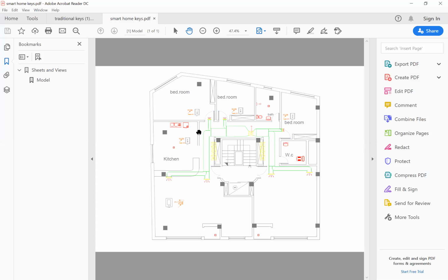On mode number 2, for example, during the day, the mom is in the kitchen and the children are in the room. Therefore, on mode number 2, the AC works with the average temperature of this panel and this panel. And for example, at night, all of the people are in their rooms. Therefore, we said the AC only works with the temperature of this room.